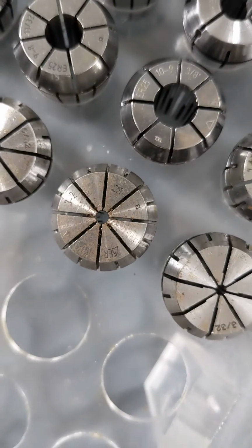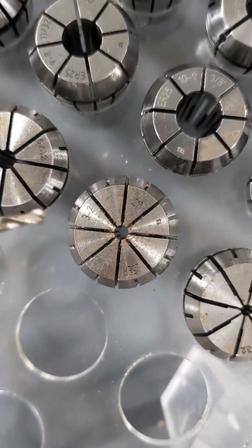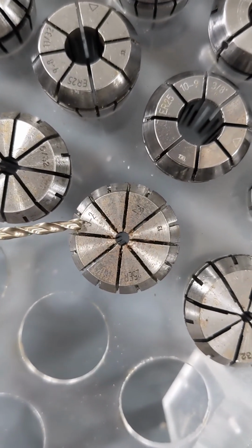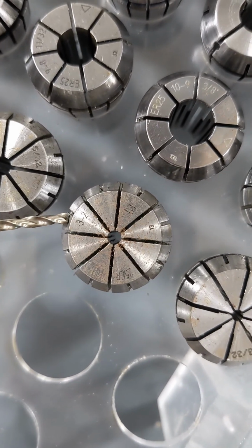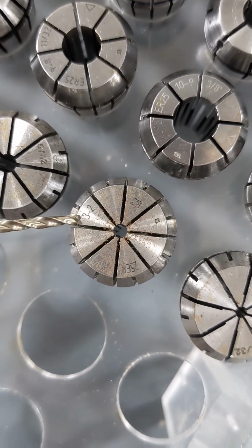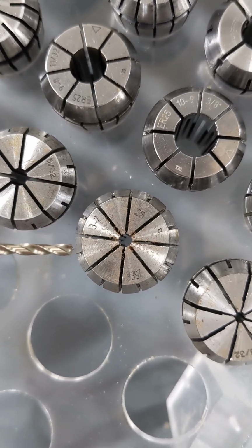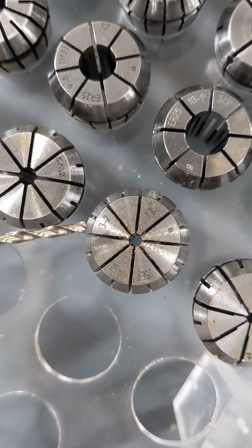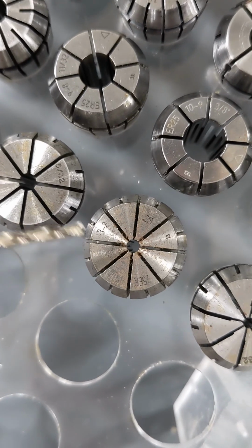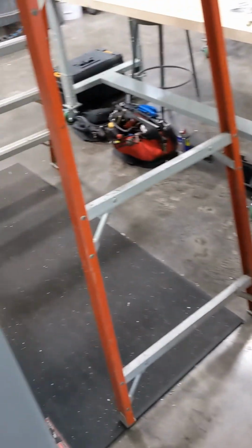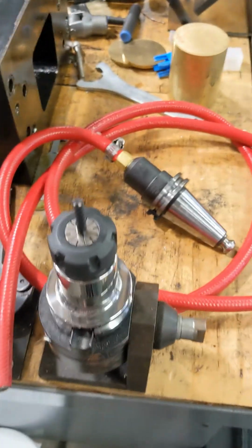You can also check on the face of these collets. They tell you in millimeters usually what diameter they're meant for. So this one goes from 3 to 2. This is 100 thou, which is less than 3 millimeters and more than 2 millimeters, so this collet will work for this tool. I moved over to the side of the Akuma.